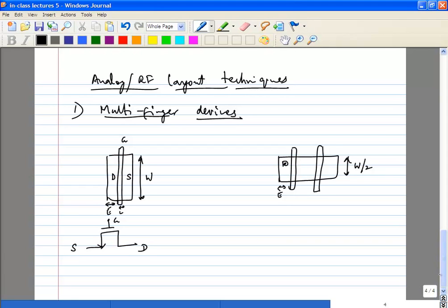Those are all things which are very important, and there may be cases where you really want to widen out this E, because if the transistor is operating at a very high current density, you might want to have more contacts. Contacts also have current density requirements.